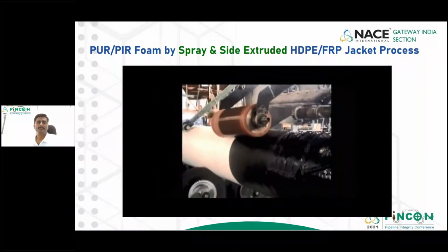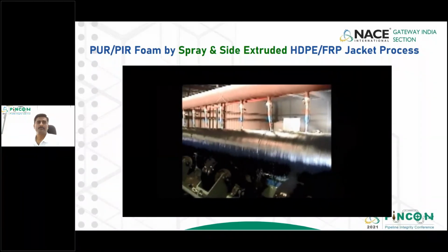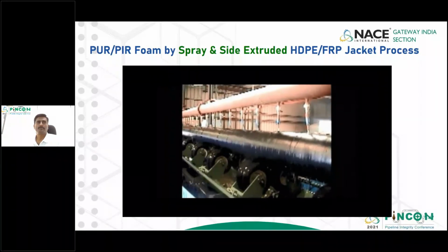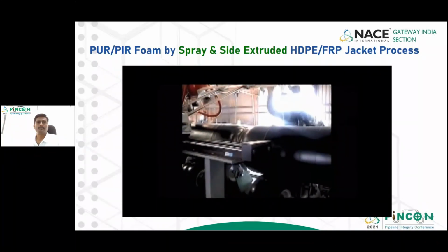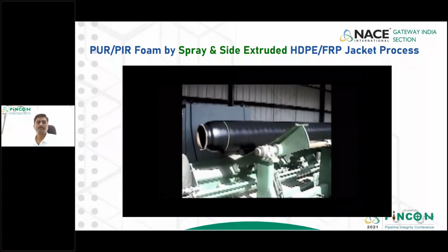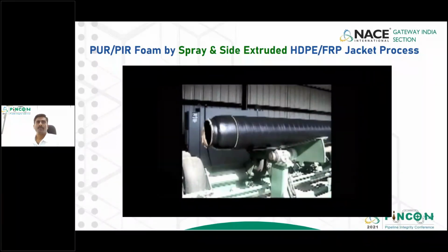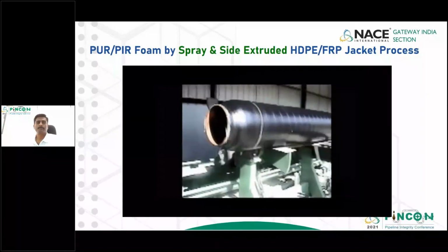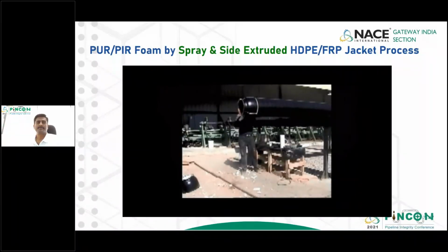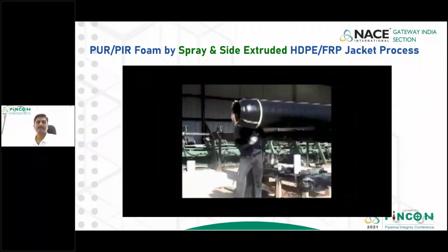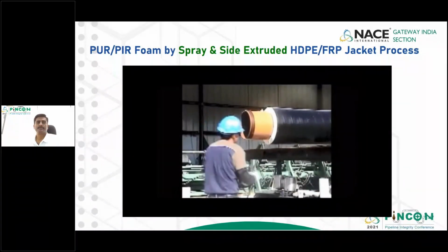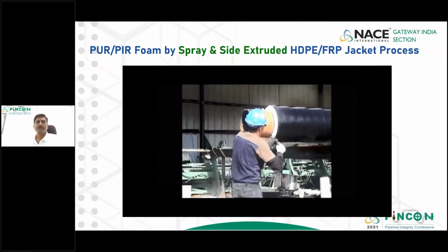Multiple wraps of the molten film result in a seamless polyethylene pipe along a distance of 20 to 25 feet. After the polyethylene is sufficiently cooled in the station, the unloading arms automatically transfer the finished unit to the unloading racks. The cutback portion of the insulation and jacket is removed from the end of the pipe. The end surface is cleaned up and will be coated with a moisture barrier. This is one of the best methodologies of doing the factory insulated piping, which I have shown in this slide to prevent the corrosion or insulation.